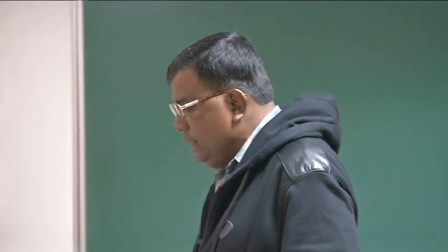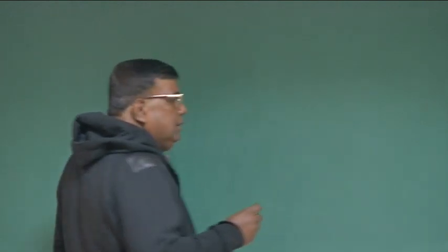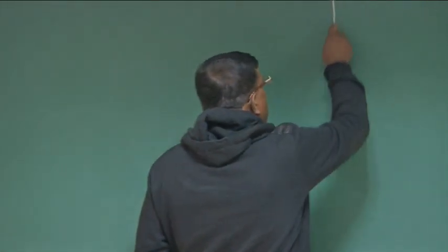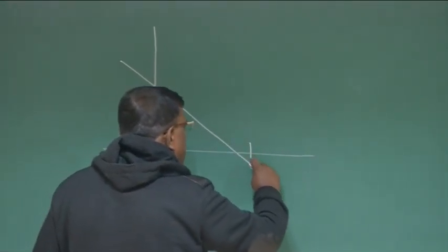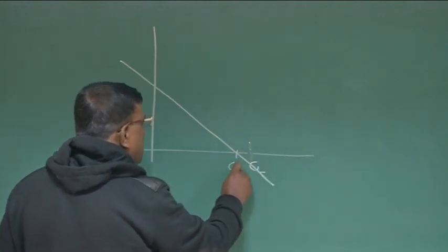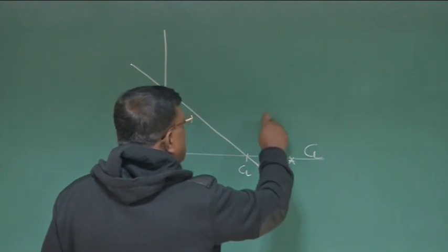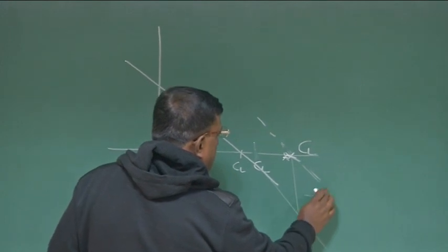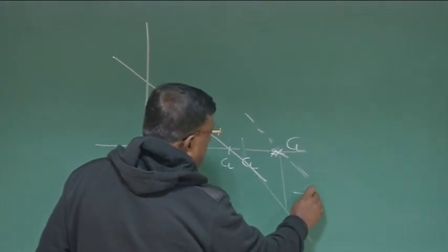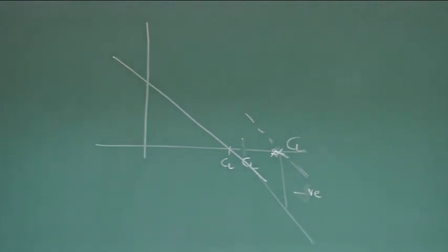So let us again revisit when we are talking about floating tendency or a stick-free case. What is the necessity to define a stick-free case? Please recall, we know one thing, that if an airplane is flying at this CL, and now you want to fly at this other CL, then so much negative pitching moment the aircraft will generate by itself.